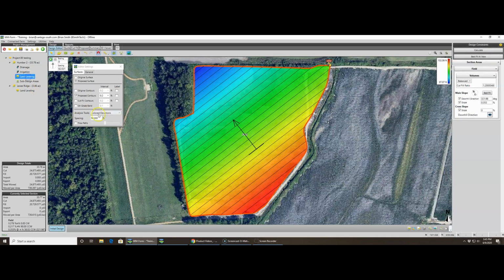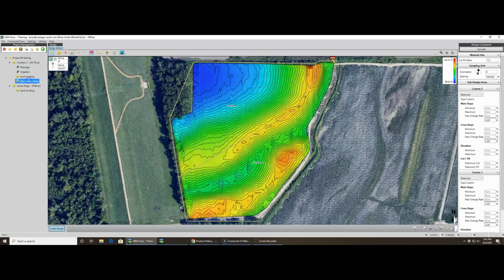Now from my land leveling best fit, I come up with 321.98 degrees. Okay, let's just go ahead and take that degree in my custom areas. Let's put that orientation as 320 just to clean that up. Again, here's this spacing, same thing as before. The spacing is a grid sampling of how many triangles it calculates within a grid.